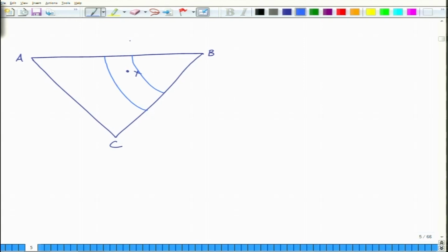So, this is at a temperature, as we went through last time, T1, T2, T3, T4. You have temperature T1 greater than T2 greater than T3 greater than T4. So, T1 is the temperature at which solidification begins, and T4 is where solidification ends, okay. So, T2 and T3 are the intermediate temperatures. If T2 and T3 are intermediate temperatures, then you can draw the tie lines.